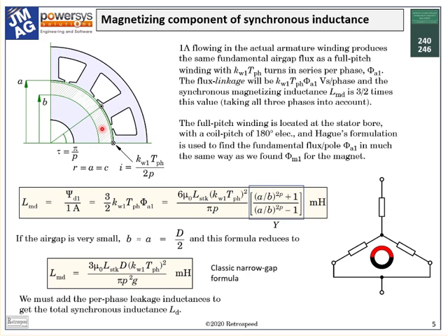But in the surface magnet motor, the effective air gap includes the radial length of the magnet in the direction of magnetization modified by the recoil permeability, and it's much bigger. In fact, this value is 8.62 millimeters compared with the physical air gap of only 1 millimeter. This means that the flux can spread out in the tangential direction, increasing the permeance and therefore the inductance.